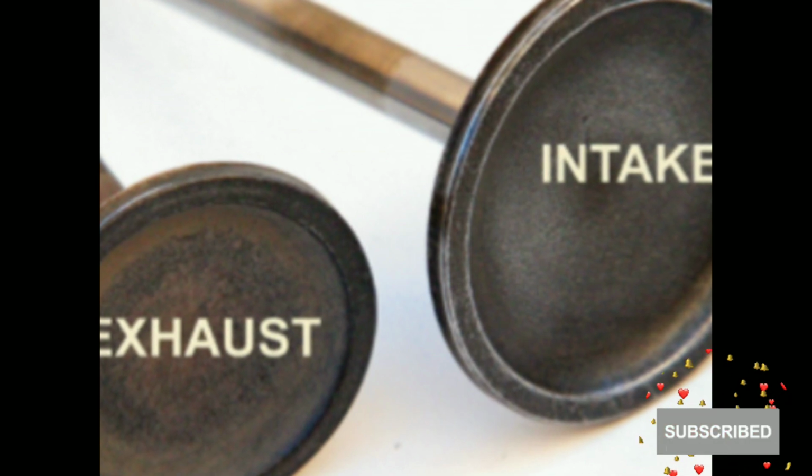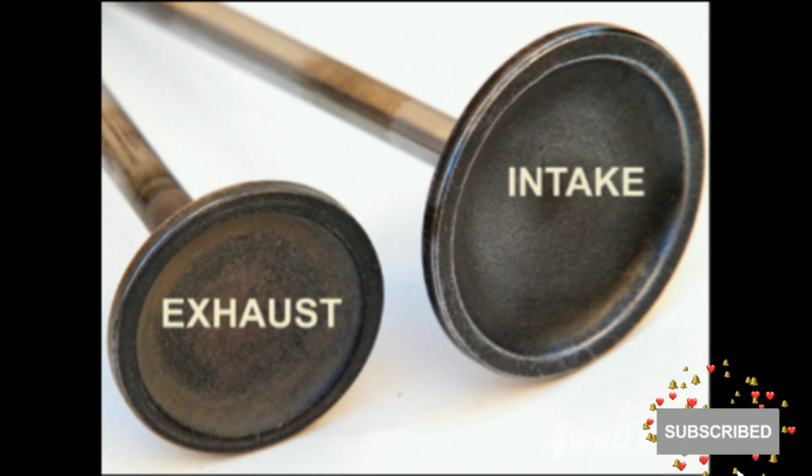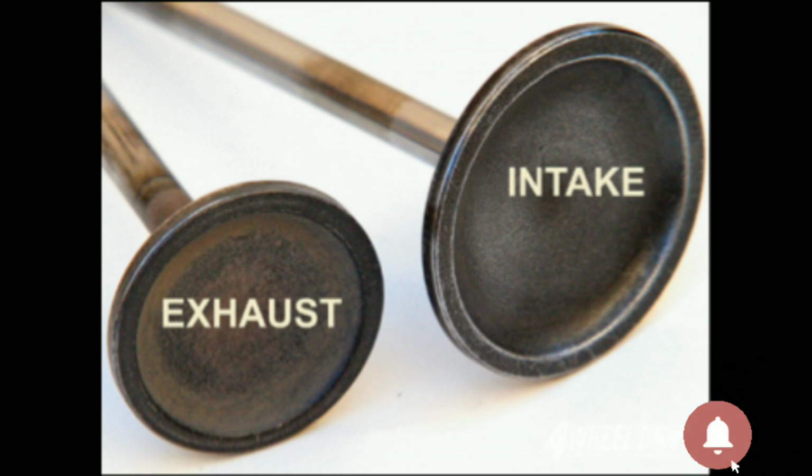This is because, in order to admit a lot of air, an intake valve has to have a wider head diameter to admit plenty of fresh air into the engine in order to boost engine torque. As you know, the more fresh air admitted into the engine, the more engine torque will be delivered to the driver wheels through the transmission system. This is one of the methods of boosting engine torque.